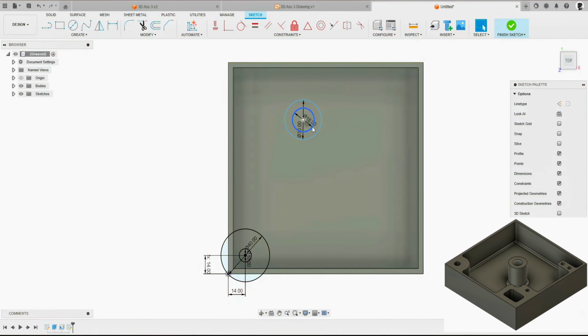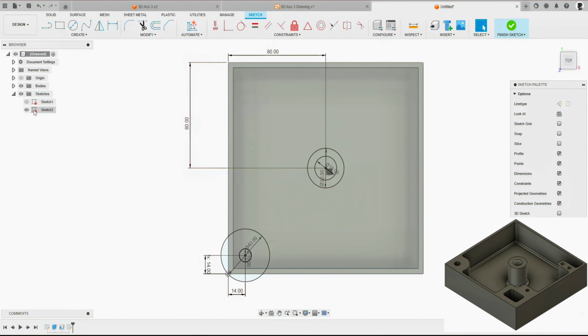Up at 18 mil there. Let's dimension this from the outer wall. That's a dimension at 80. And then dimension this from the top horizontal at also 80. So that's centered. Everything's in black. Everything should be fully constrained. We've got our red padlock there. That's looking good.